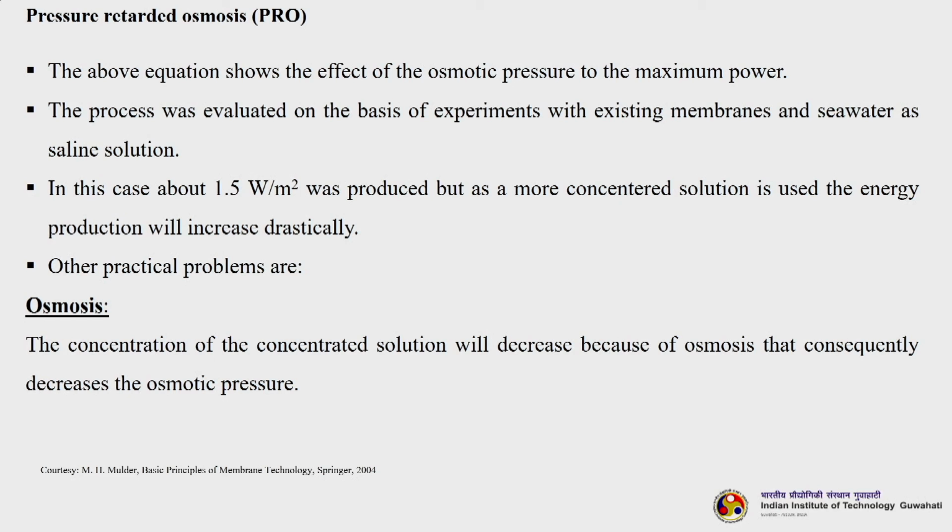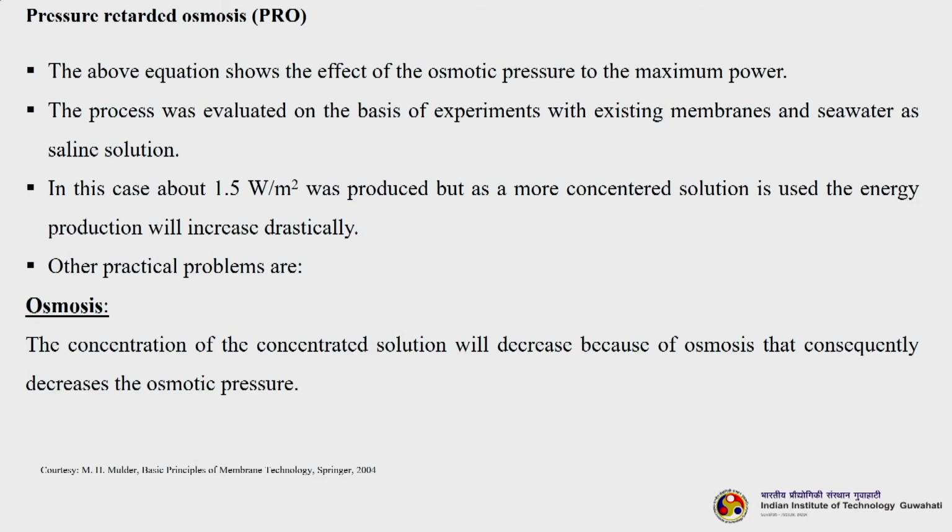Other practical problems associated with PRO is the osmosis. The concentration of the concentrated solution will decrease because of the osmosis, which consequently decreases the osmotic pressure. So, when PRO is going on, some osmosis is also happening, and that is creating a problem because it will decrease the concentration of the concentrated solution. We understand that the more concentrated the solution, the more will be the delta pi, and the more electricity will be produced.